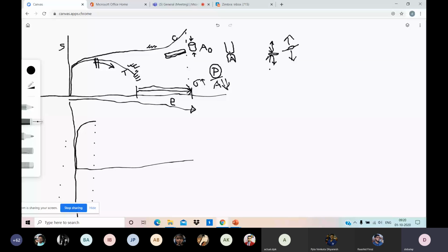If there is bulging, suppose this is, I am showing bulging. Whenever there is stretching, that causes cracking. So you will find in a bulged component, like you see stretch marks, it's something like that. Whenever some region is getting bloated, then there will be a tensile force, and that is secondary tensile stress. But with secondary tension, the cross-section is also increasing. So will the cracks that form, will those secondary cracks lead to failure?